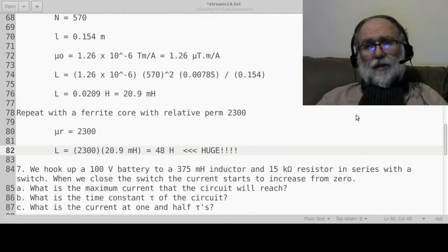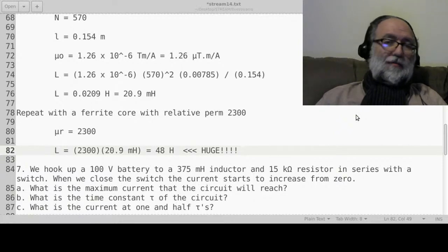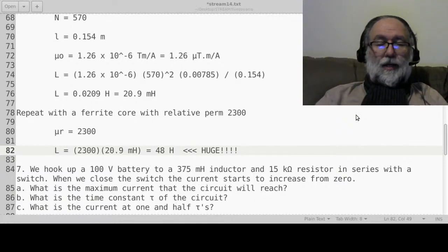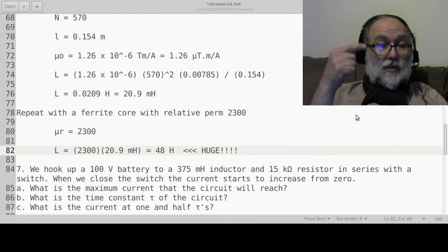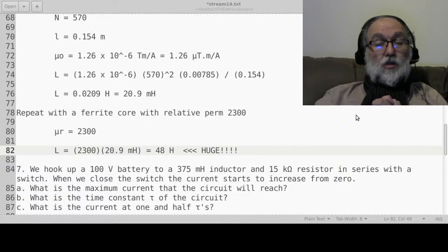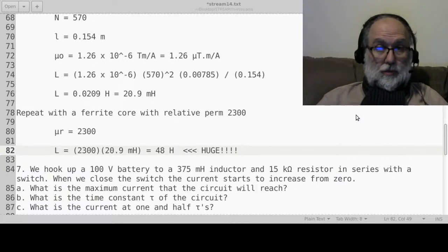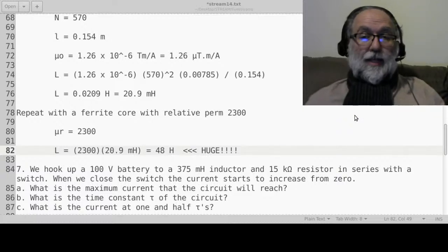By the way, if you want to see an inductor, if you have a computer that you can see inside, most of you have laptops which you can't open up, you look on the motherboard and you'll see these coils of wires that look like solenoids, but in the middle of them there's usually some kind of a black bar, and that black bar is usually some ferromagnetic material, because the presence of that ferromagnetic core greatly increases the inductance. Okay, so that answers that question.